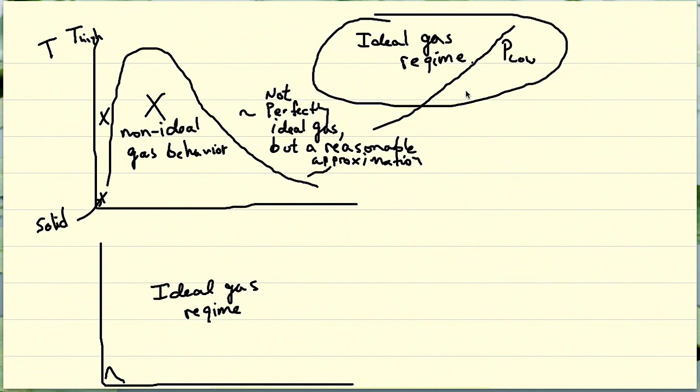Okay, so you'll also note on this diagram that I drew down here, if we were looking at an ideal gas, where would the saturation region of that ideal gas be? It would basically be way down here, close to the ordinates, right? So this is the basic idea of an ideal gas, is that you're way out in this very low pressure, very high temperature regime of the TS or the PS diagrams.